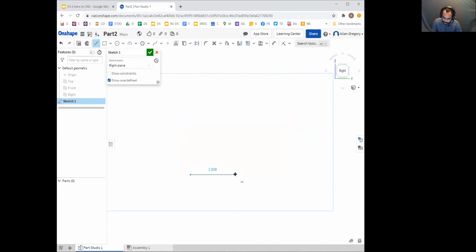We very rarely want to draw a line ever so slightly not straight, right? It would be really tricky to try to draw a line somewhere between those two lines. So it's very handy for OnShape just to give us that nice snap, and we know we're drawing a straight line. Same thing happens with going up. I can come in and do that. We can come over. If I select this, it'll let me just drag it straight up, and now I know I'm straight above that line already.